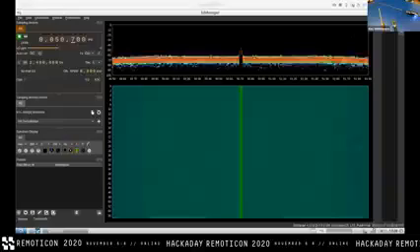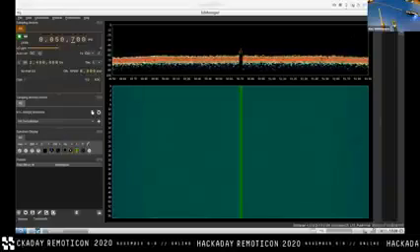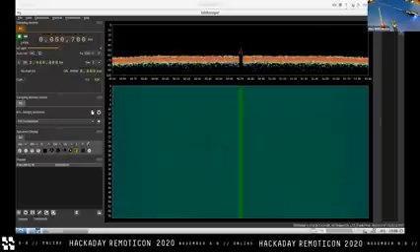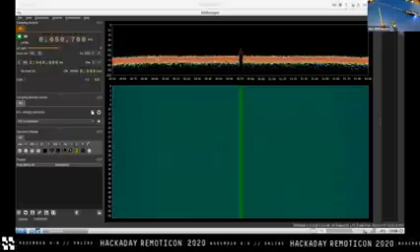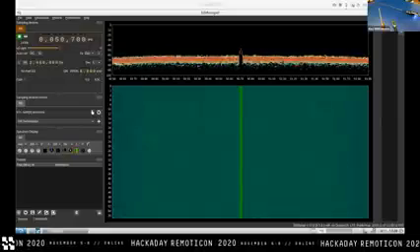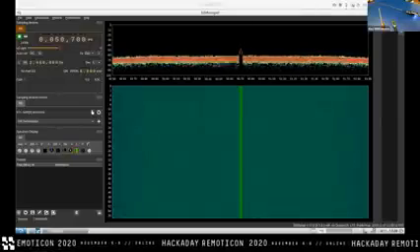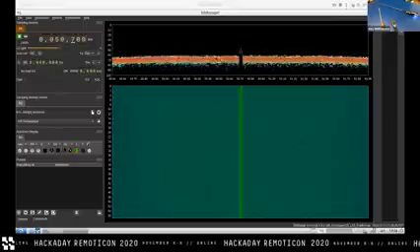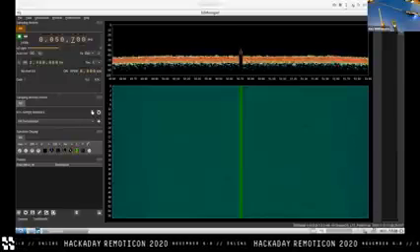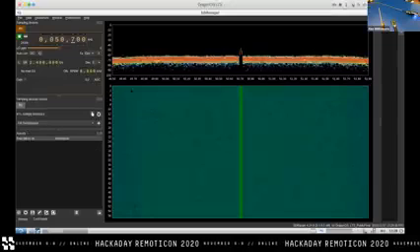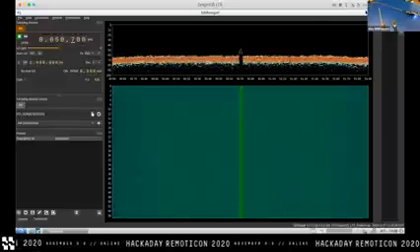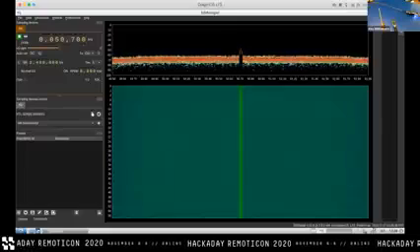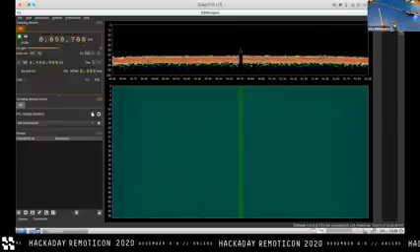And then you can wave your magic wand around at the tuning frequency and figure out exactly where on the board it is. I'm sure you can probably whip that together with SDR Sharp or GQRX, or one of the SDR tool chains. I'm sure GNU Radio, you can probably whip that together in 2 seconds as just an RF power meter at the tuning frequency. But it would be cool to do it with this same DPO style view so that you can see what's going on around it as well. Oh God. Okay, cool. It didn't go to sleep. I thought that was going to be another restart. But again, this is only really useful if we've got this sort of narrow bandwidth. So let's go try something else.